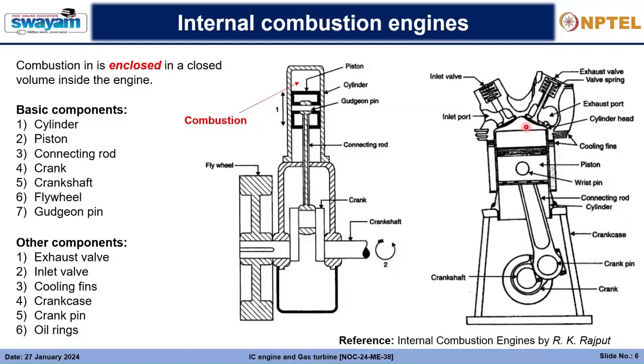Then we'll have these cooling fins. The cooling fins actually are provided to cool down the engine. So when the combustion takes place, there is a huge pressure and temperature, and not all the pressure and temperature is utilized to drive this crankshaft. So eventually, some amount is absorbed into these metallic bodies, and they get heated up. And we need to cool that also. So we have the cooling fins and the cooling jacket also. This is the cooling jacket.